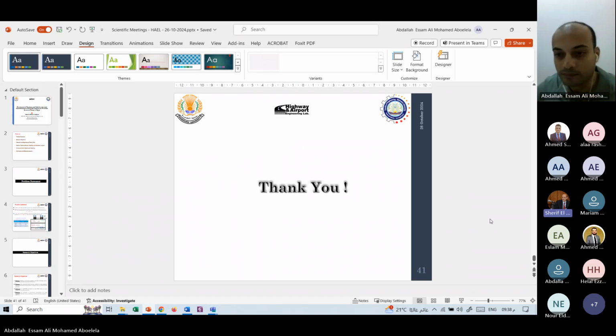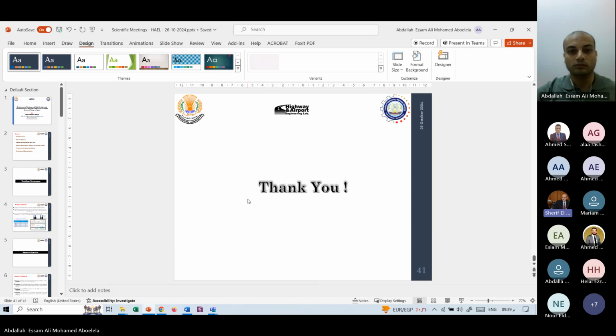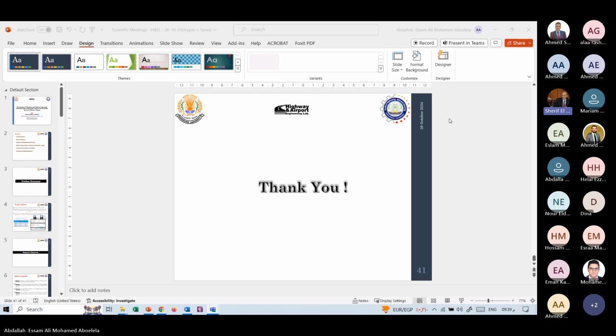Thank you. Let me mention one thing. This project was a continuation of another project that was completed with the National Institute of Transportation. And it was focusing upon developing an MR-CBR relationship for the granular base and sub-base materials. And the idea behind the first project was that we found that the MR-CBR correlation that was implemented in the previous Egyptian code was yielding MR values that, we feel, taken from the South African manual, were really high compared to the properties of the Egyptian base and sub-base materials that we are familiar with.